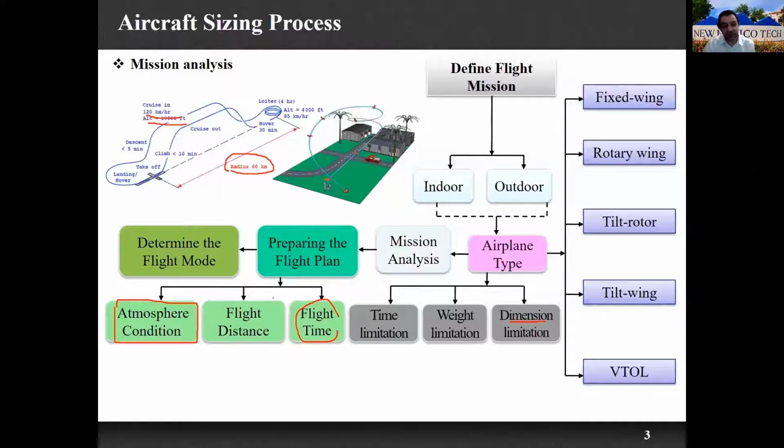There are different varieties of flight modes that we will discuss later in this lecture. For example, if you want to make an airplane which can hover like a helicopter, the design would be different from fixed-wing UAVs, which just have a front rotor or propeller that generates horizontal thrust. Or you can combine rotary wings with the fixed wing, and eventually you can have a tilt concept: tilt body, tilt wing, or tilt rotor drones or airplanes.